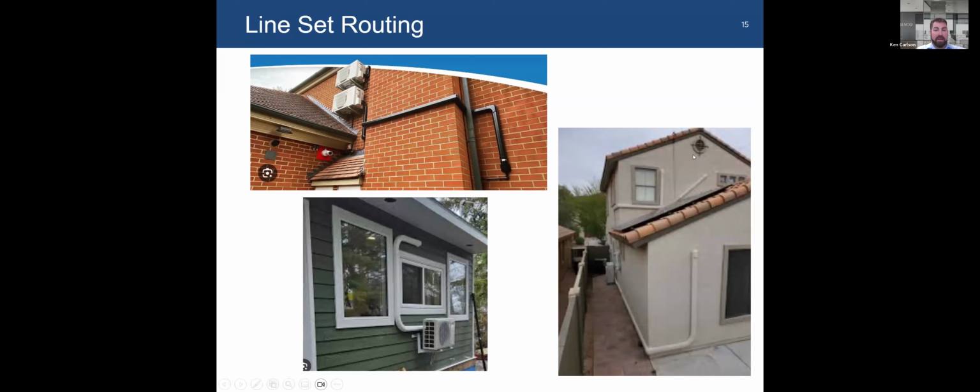If you don't have an attic, you're not putting ductwork in, or maybe it's just a quicker installation to put mini splits in. You'll have to consider how you're going to run your line set. And this even applies for a standard split system if you're going to put an air handling unit in the attic. You need to get lines, refrigeration piping, from the outdoor unit to the indoor unit in an existing home, unless you're going to rip out the walls, which most people and contractors don't want to do unless the homeowner asks for it.